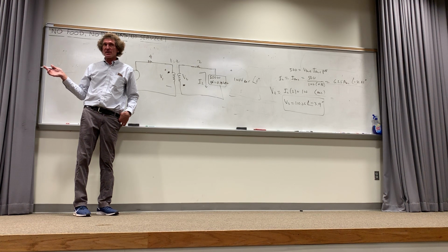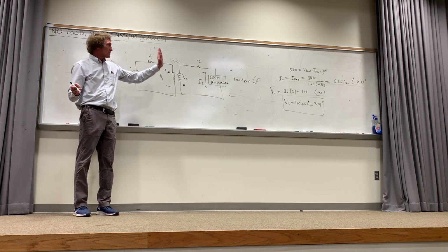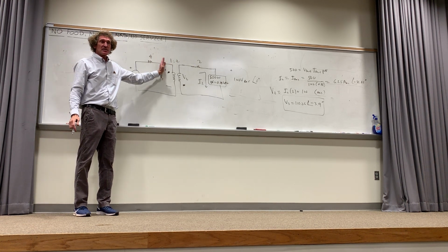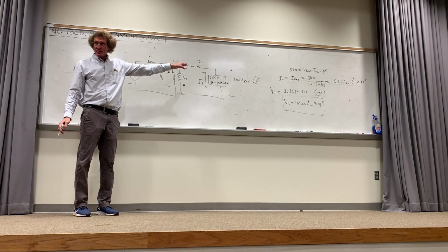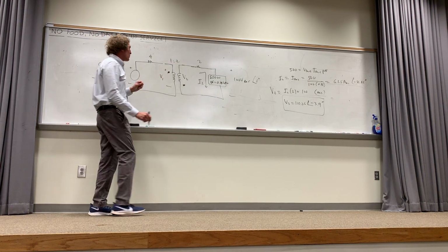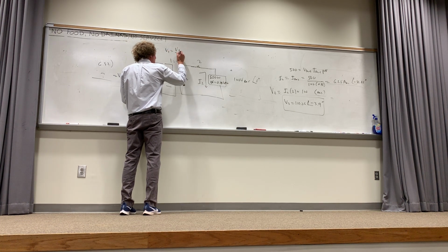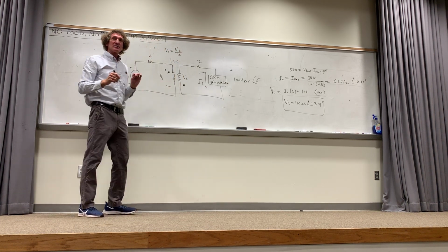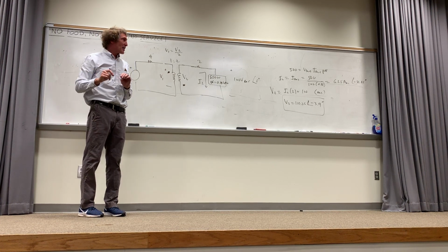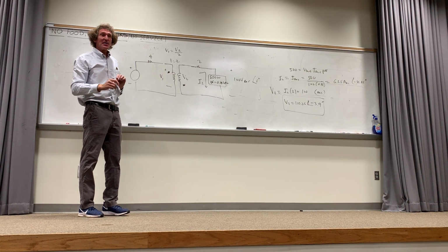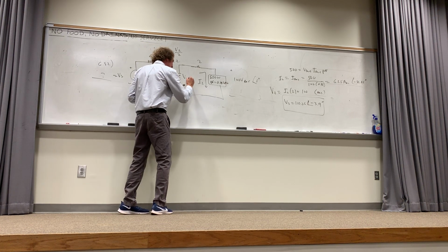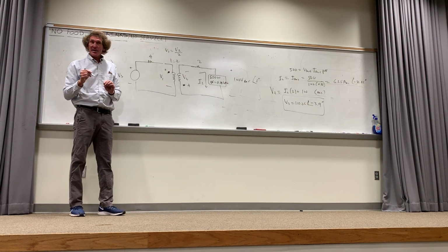We could write the turns ratio equations every time, but you've got twice as many turns on the secondary as this primary, twice as much voltage, all right? That means voltage V1 is just V2 divided by 2. Now here's the kicker that I didn't say anything about. You'll notice this V2 is what? See that? Isn't that right?